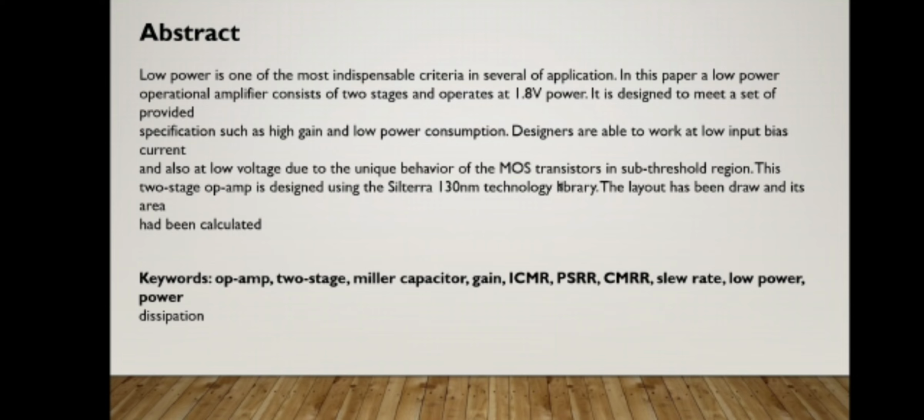Designers are able to work at low input bias current and also at low voltage due to the unique behavior of MOS transistors in the sub-threshold region. This operational amplifier is designed using the Cadence 130nm technology library. The layout has been drawn and its area has been calculated.